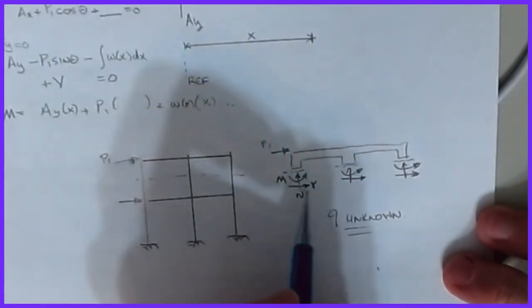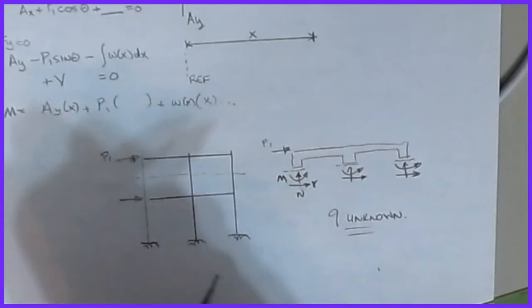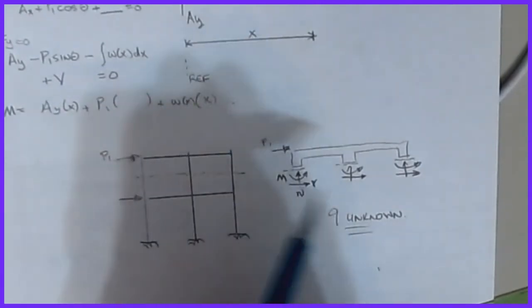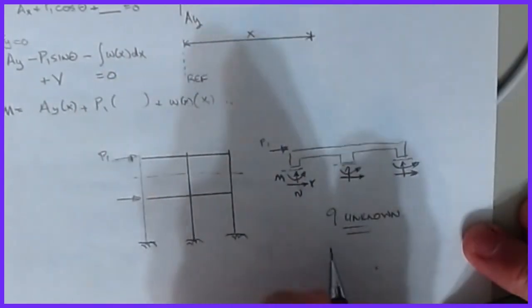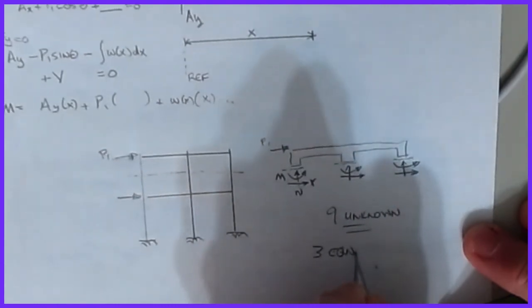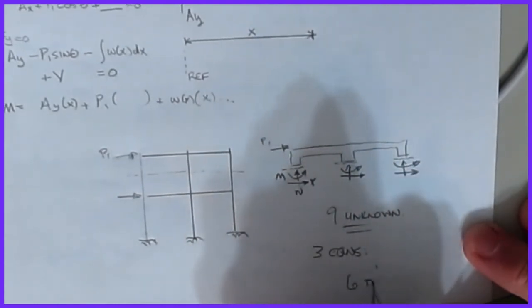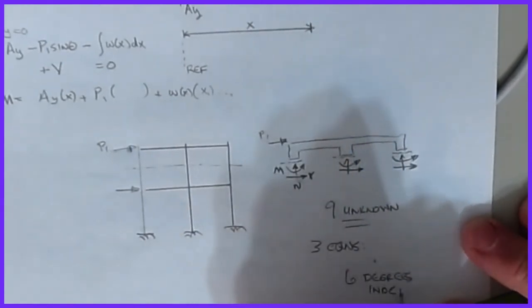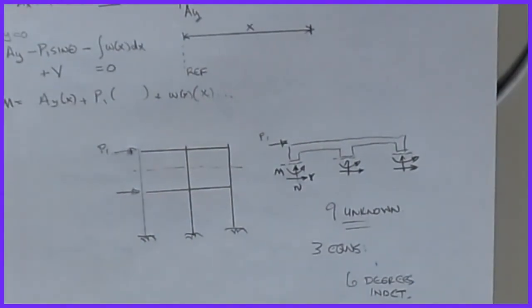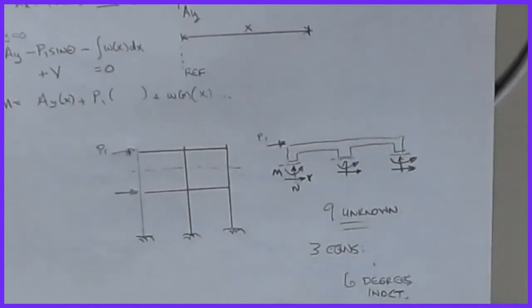So you can see that in a hurry, if I start getting sloppy in how I cut things, I can make a royal mess that there's no possible way I can solve using just statics. This becomes highly indeterminate because that free body diagram still only has 3 equations, and so I've made this 6 degrees of indeterminacy, and that's a problem. So we've got to be very careful with how we start to explode this and proceed in a logical setup. That's the nature of what internal forces are doing and how we're starting to look at those.